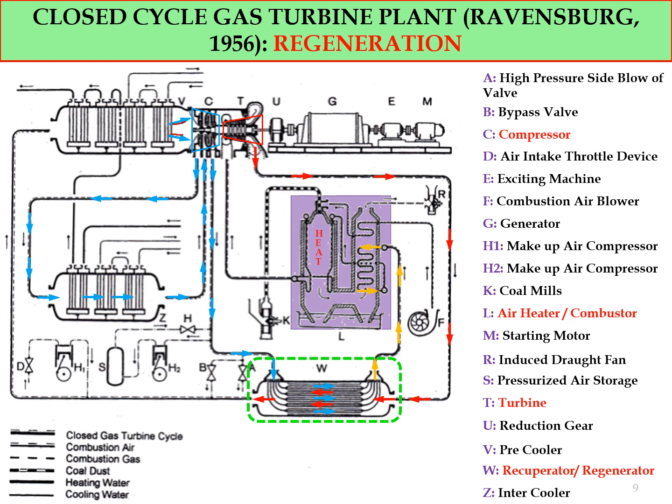The preheated air from the compressor goes into the combustion chamber, as you can see in the green arrow, and the output of it is high temperature. It goes into the turbine, and the exhaust of it will reheat the compressor air, which I already explained before, and the air will go back into the compressor inlet. So this is the complete cycle or complete process of the gas turbine plant with the regeneration.